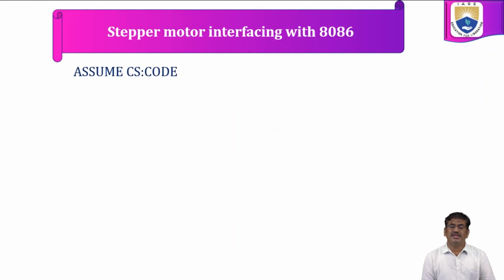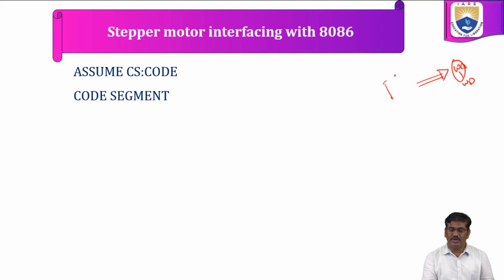So now for interfacing the 8255 to the microprocessor for stepper motor interfacing, we require the stepper motor with 4 windings, winding A to winding D. These pulses we have to send from the 8086 processor. However, in between the processor and the stepper motor, we have the 8255. As we are sending only pulses, one port is sufficient. So we are going to use port A, as an output port.